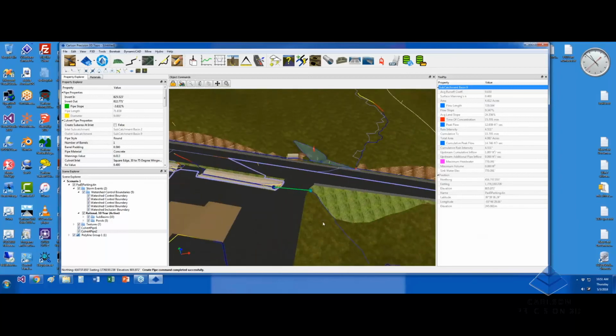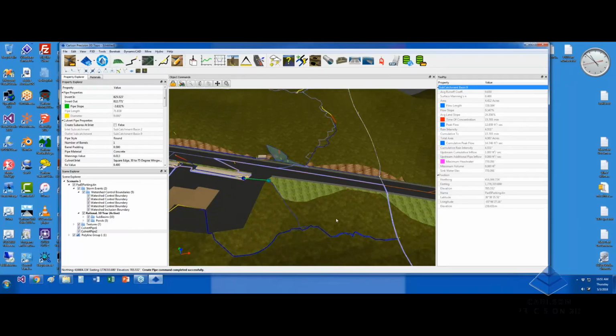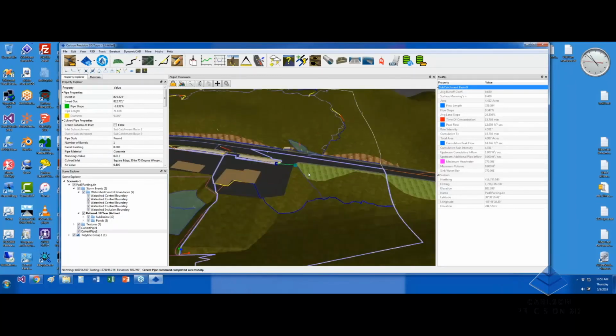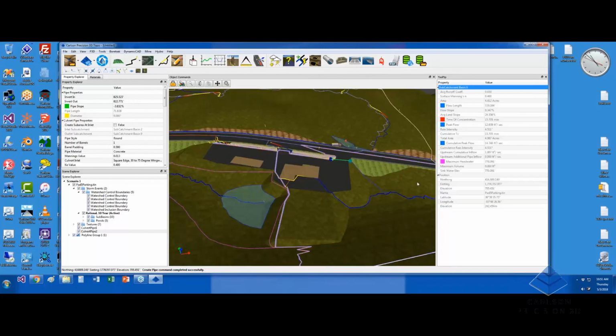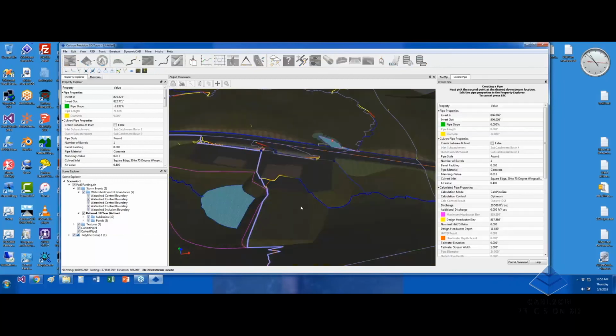And one other thing that I want to show you is that in this subbasin 9, which is the basin that's actually catching the water, you'll notice that we have these cumulative rain intensities and cumulative inflows. What's happening is that this is the peak flow that's calculated just for the subbasin, but the influence of having these two culvert pipes connected across here have added this cumulative flow and modified the rain flow. And you'll notice that we're at 14.764, but what I'm going to do is drop a culvert from this pond down into this nice little natural channel at a -2%.